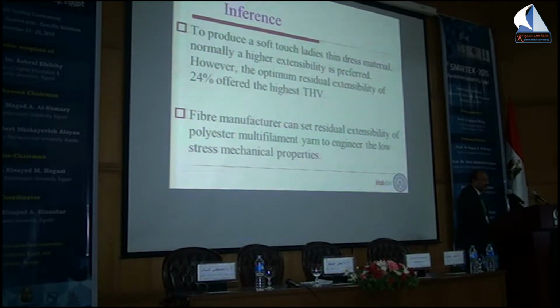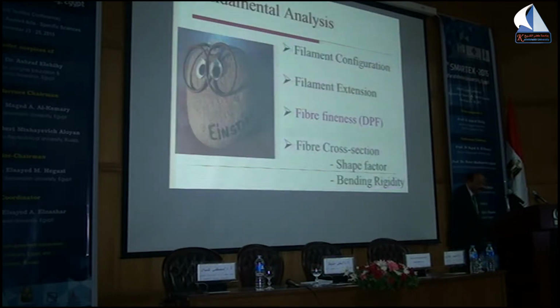So to produce a soft touch ladies thin dress material, the samples were used for ladies dress material. Normally we think that higher extensibility is preferred. However, this study shows the optimum residual extensibility is about 24%. If you go beyond this, then again hand value falls.